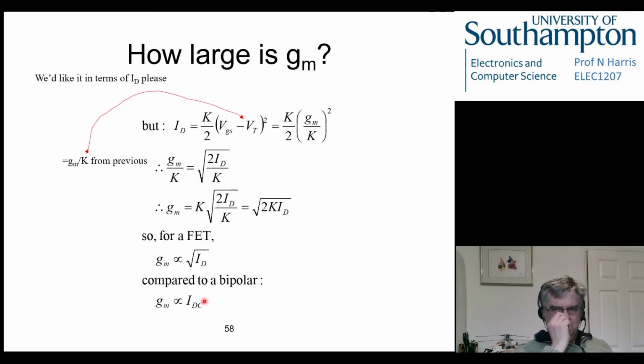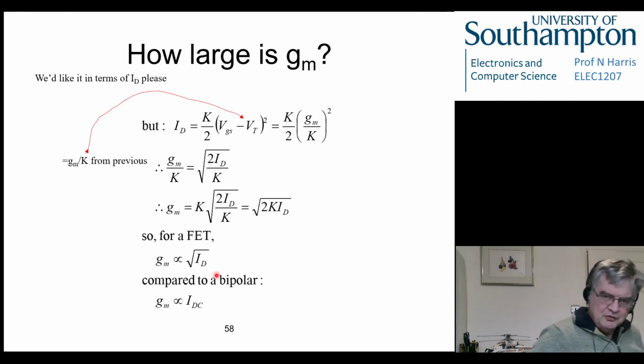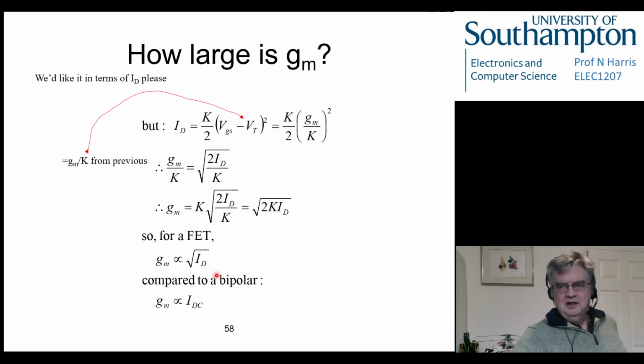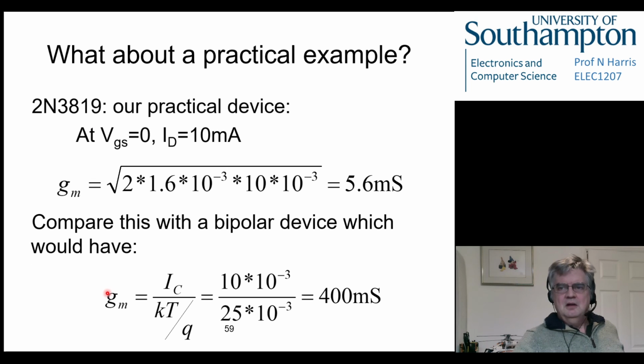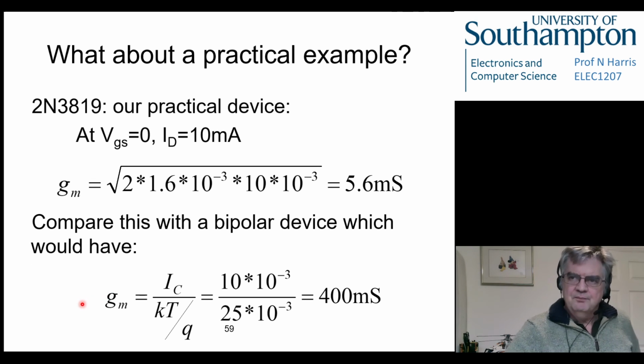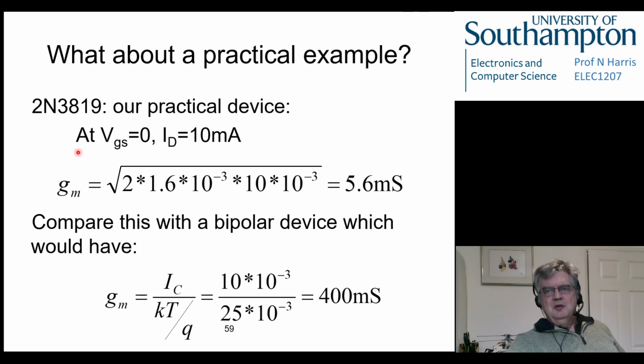This sort of gives you a bit of a clue that they might not be quite so good for amplifiers, because their internal gain constant, this GM, is going to be lower because it's related to the square root of the bias current going through it, not related to the linear version of that. And the reason why that becomes important is because if we then start to put some numbers in...